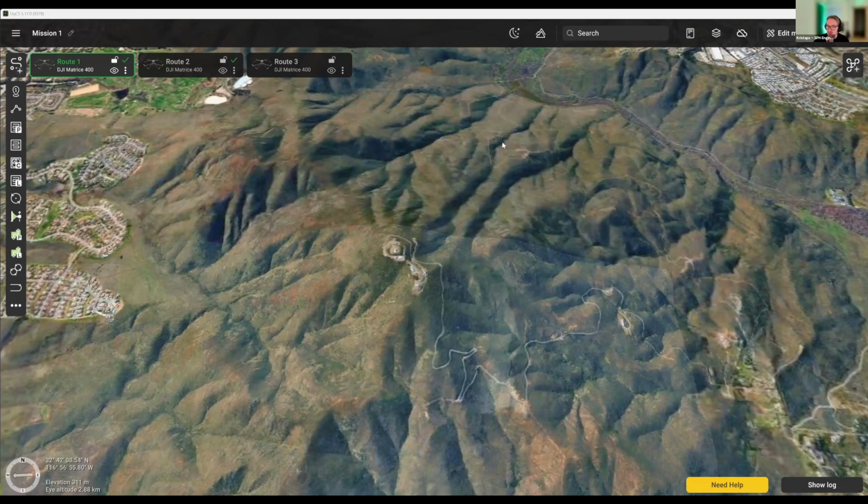Okay, and also from Robert, there's a question. What do you recommend in steep terrain for LiDAR flight planning? I think when we get into the flight plans, I'll try to talk about some points. But in general, when you're flying over very steep terrain, I think it's a good idea to use, for instance, the smart AGL flight altitude algorithm that we have built into UGCS, which also can make your flights a bit safer. But there are some caveats with this as well. So I'll try to cover all of this.